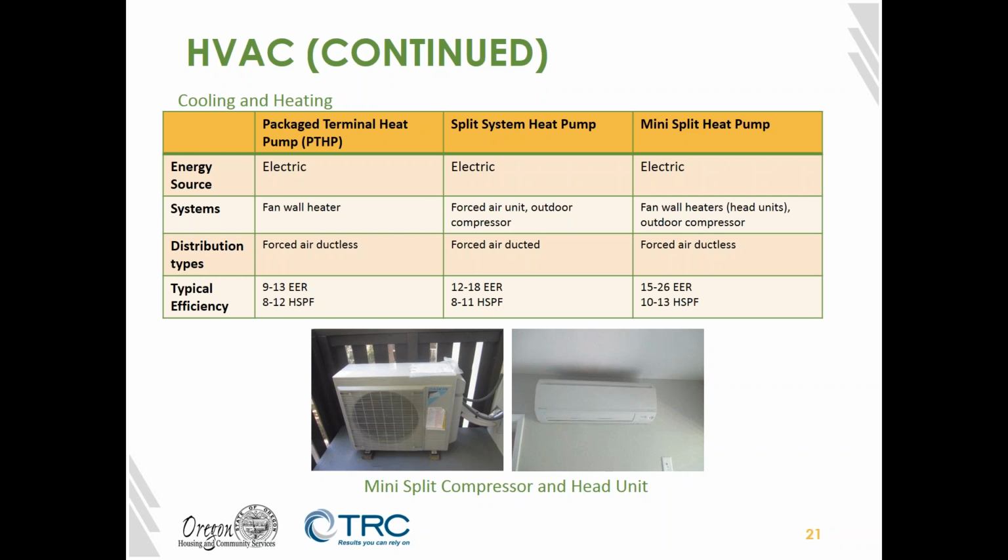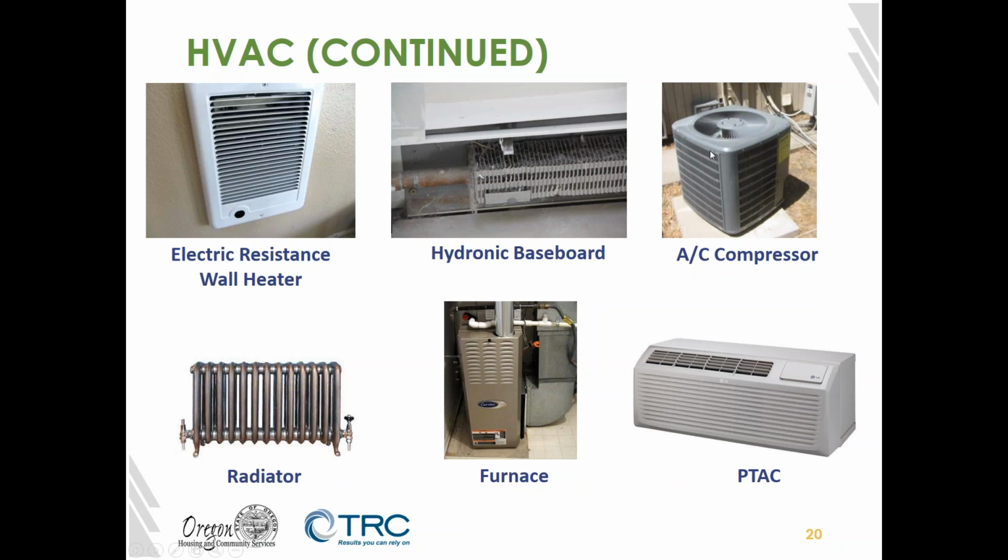They're very efficient, just like with the water heaters. The heating is multiple times as efficient as the non-heat pump option, and the cooling tends to be a little bit more efficient also. The heat pumps can come in several flavors. Package terminal heat pump is the same form factor as the package terminal air conditioner. A split system heat pump is the same thing also, where the heat pump will just be that outdoor unit, just like this air conditioning compressor. And then it just goes into a fan unit on the inside.